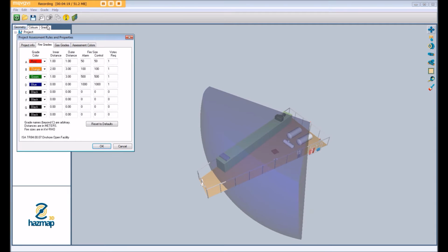So when we look back at the grades, that's obviously crucial for different fire sizes. We don't need to change this cone based on what fire size is applied within the area. The software will recognise what target fire size is needing to be assessed within that area and will automatically calculate the coverage based on which flame detector has been installed into the area. And that's entirely based on third-party verification of flame detectors, third-party provided data that Micropack have gathered, which is completely third-party validated and completely open for the users to review that data.